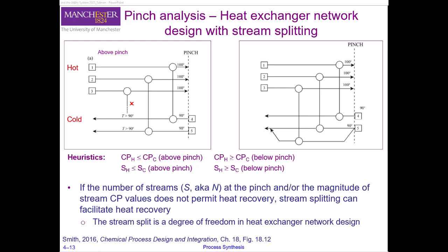Because the pinch analysis follows these heuristics of CP and the number of streams, sometimes if these heuristics are not fulfilled, we cannot really have a good match between the hot streams and the cold streams. So stream splitting is a degree of freedom that can help us make the best use of the heat source, that is the hot stream, and the cold streams.